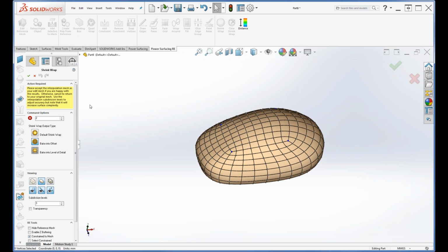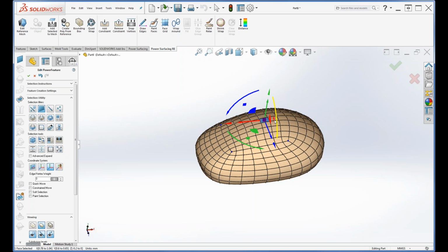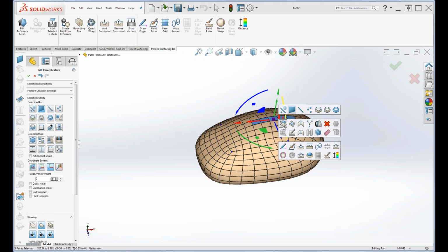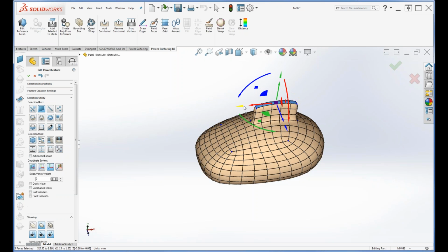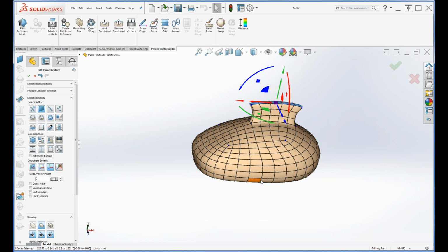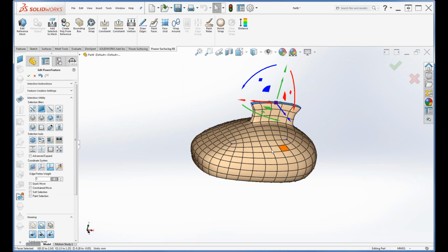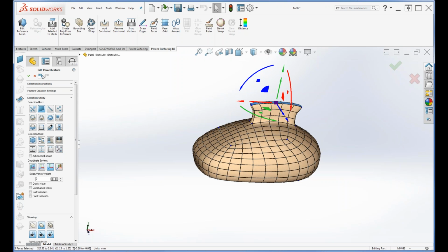You could export the sub-D, or at this point, you now have full power to model it. So if I wanted to extrude it and maybe do some other stuff, we could do that. So it's the original shape until you start modeling it, and very quick because it's no longer constrained to anything. And so that's one of our options. Now let's undo.